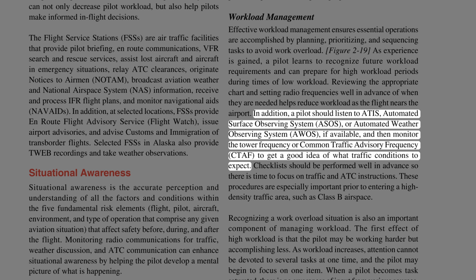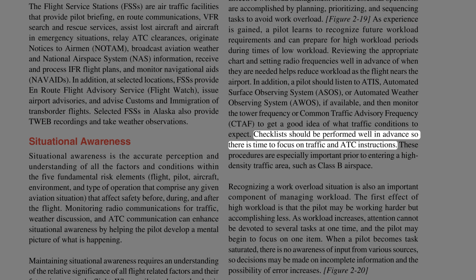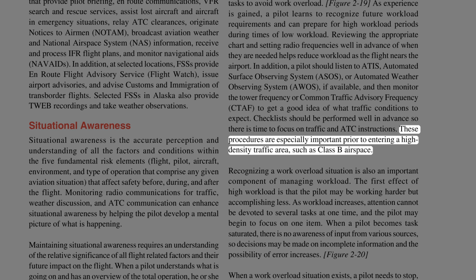In addition, a pilot should listen to a TIS, Automated Surface Observing System, ASOS, or Automated Weather Observing System, AWOS, if available, and then monitor the tower frequency or common traffic advisory frequency to get a good idea of what traffic conditions to expect. Checklists should be performed well in advance, so there is time to focus on traffic and ATC instructions. These procedures are especially important prior to entering a high-density traffic area, such as Class B airspace.